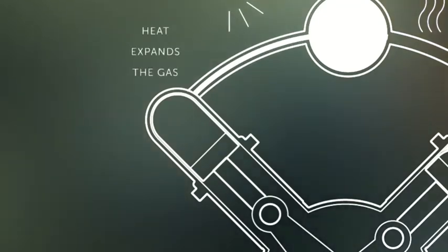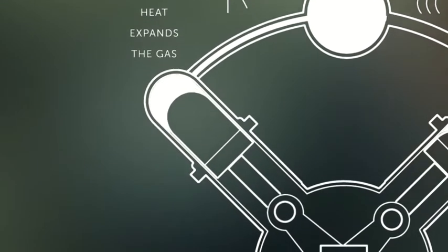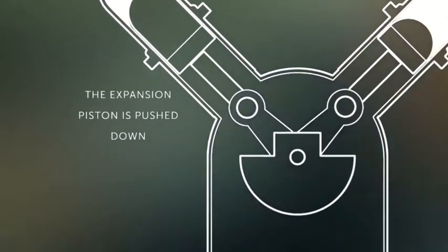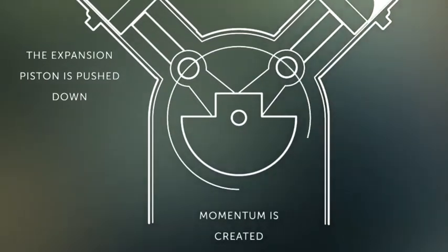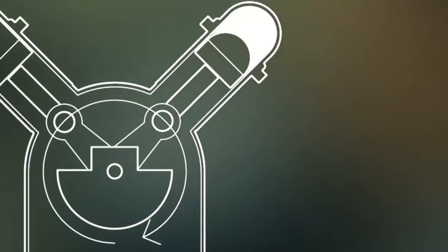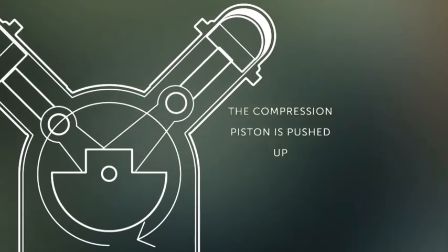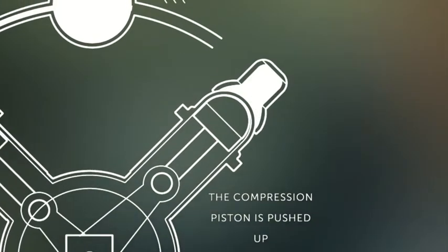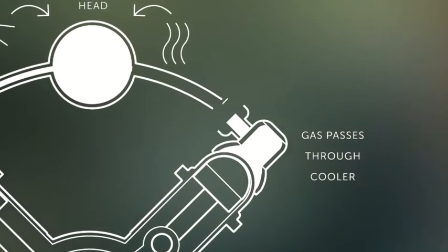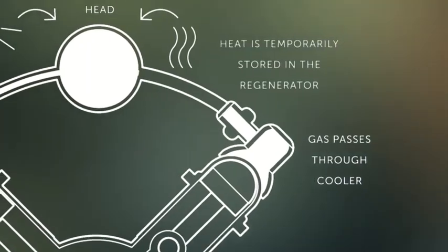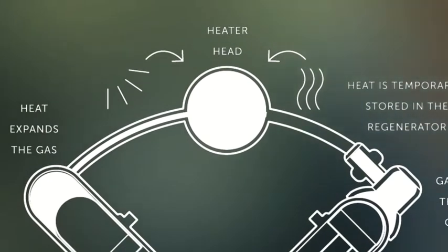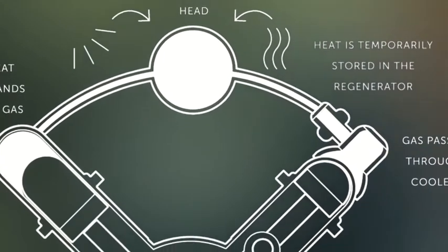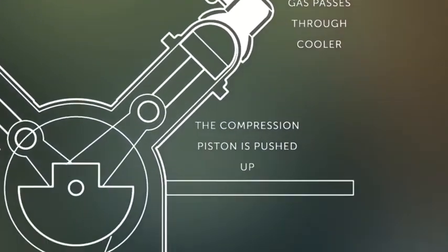When the gas is heated up, it expands, thereby pushing down the piston, and the next cycle is being cooled down and the piston goes back. The cycle is that you heat up and cool down the working gas about 25 times per second, to 700 degrees and 80 degrees. And this is the basic of the engine.